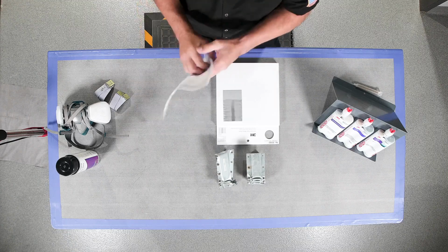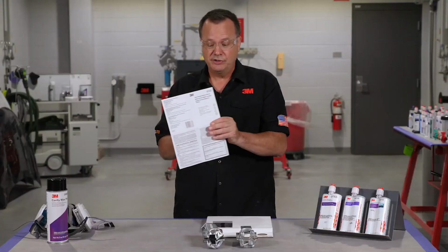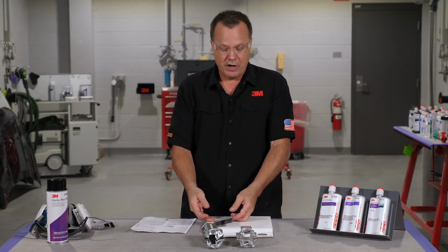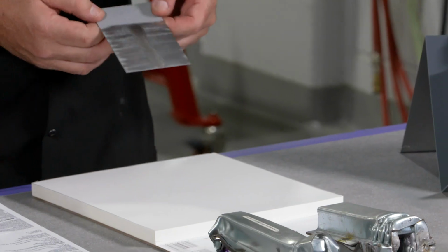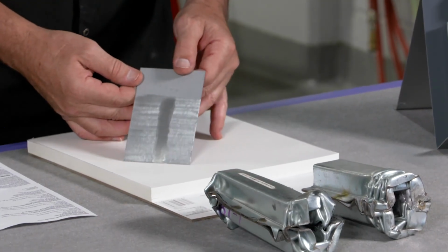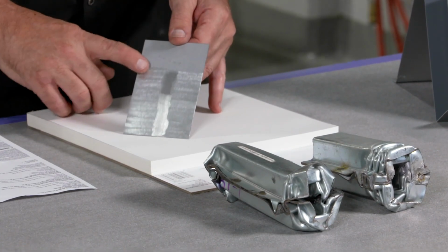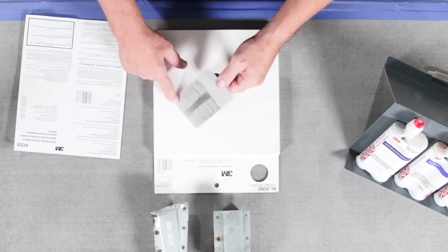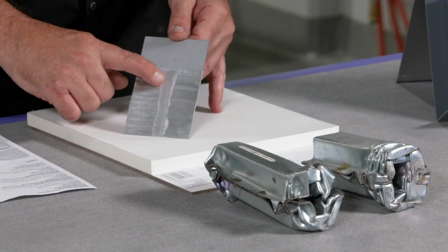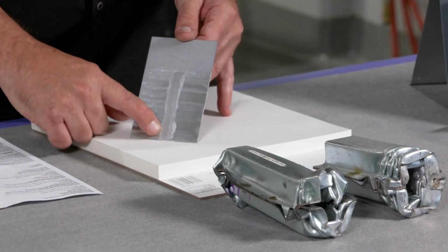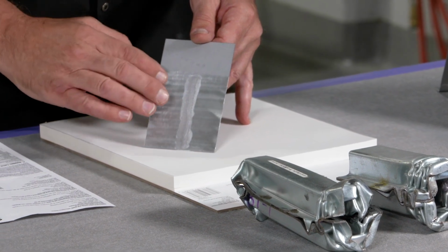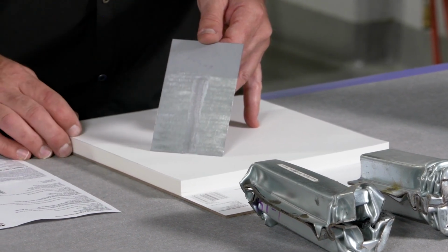So again, familiarize yourselves with these instructions. This information is in the instructions, and it'll tell you whether or not you have to remove that coating. Now this sample here shows the difference between a surface that just has the primers removed compared to one where it's been abraded aggressively enough to remove all the galvanizing or zinc coating. So you can see a drastic difference between the two.